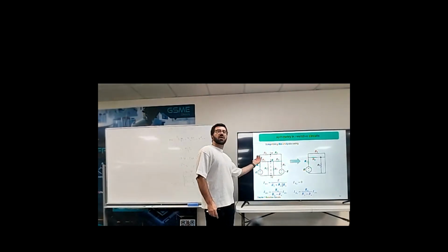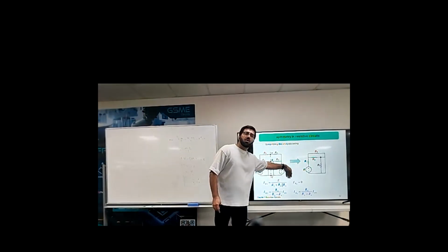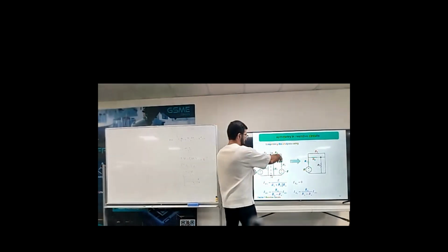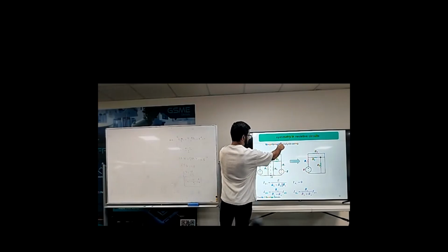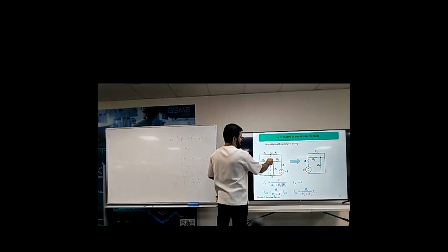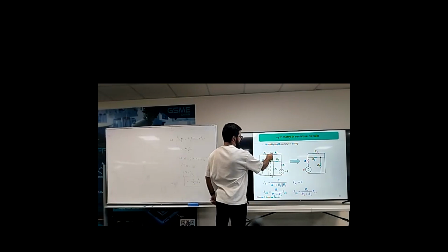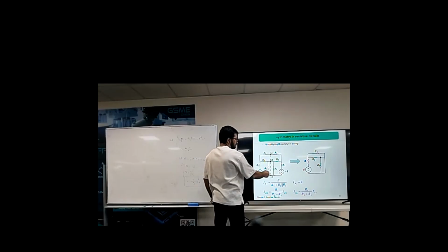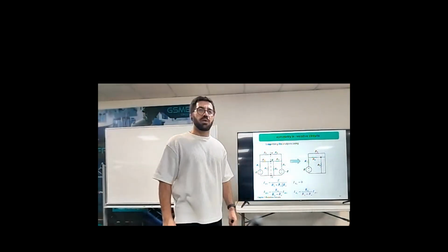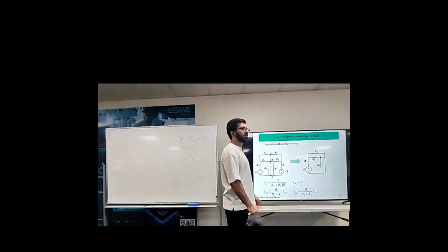If I have 2 ampere here going up, I should have 2 ampere here going down. There is a symmetry. That means if I have 2 volt here and -2 volt here, they are playing differential, which means here is 0 volt. As a voltage, they are zero because if this side goes up, the other side goes down. I can consider all these nodes as the same potential, so I can connect them together.